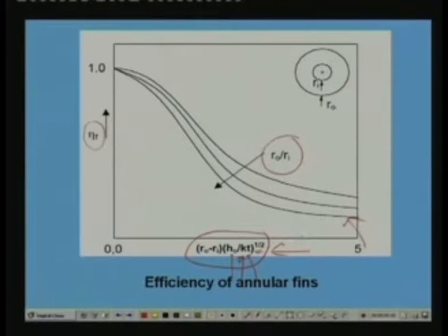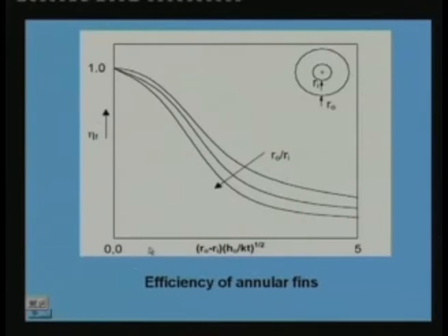So this kind of chart is available. If you know r naught and ri, the thermal conductivity, the thickness and the heat transfer coefficient, you can find the fin efficiency. So this is how the fin efficiency of a plate fin is obtained.